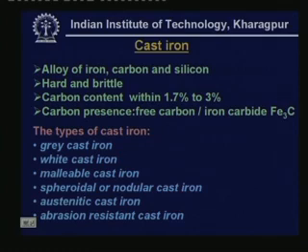That means it is only applicable in the elastic zone, and then it does not elongate. That means it does not have any plasticity character. So, that is what we call brittle. If I have a certain amount of plastic zone, then we will normally call that material ductile. That you have already heard, I suppose.